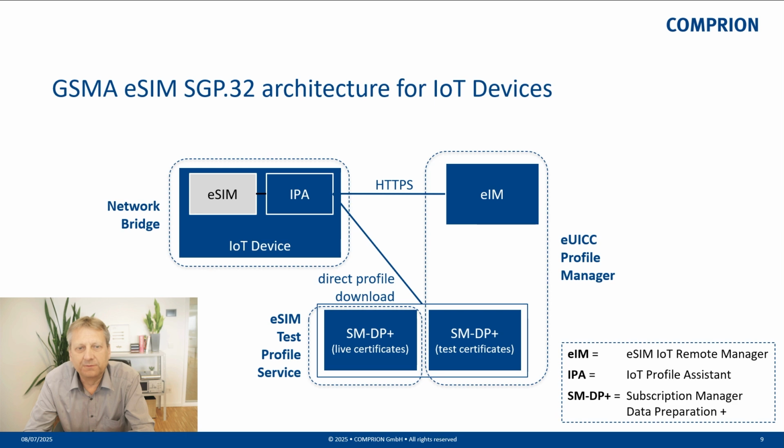And if you run an eUICC with live certificates, not with test certificates, then for the SM-DP+, we provide a service which is called the eSIM Test Profile Service. So all this together is a fully fledged end-to-end development environment where you can drop one component and put your device or component under test in for testing purposes and for development purposes.